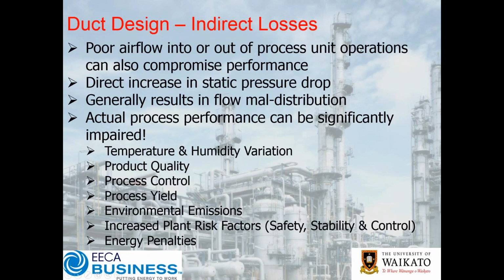So just as another point to look at some of the indirect losses now in terms of duct design, we can have poor airflow into or out of process unit operation. So this is, for example, heaters, coolers, reaction vessels and so forth. And any poor airflow in and out of these processes will compromise their performance. So ducting will directly increase static pressure drop, but generally bad ducting is also going to result in flow maldistribution.